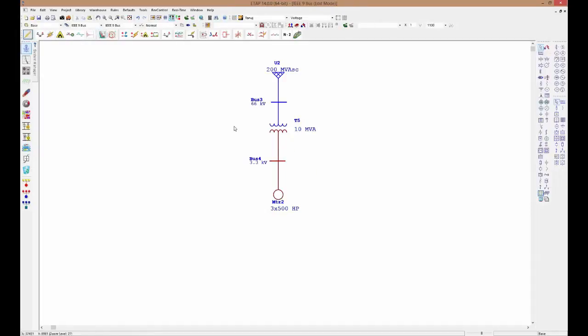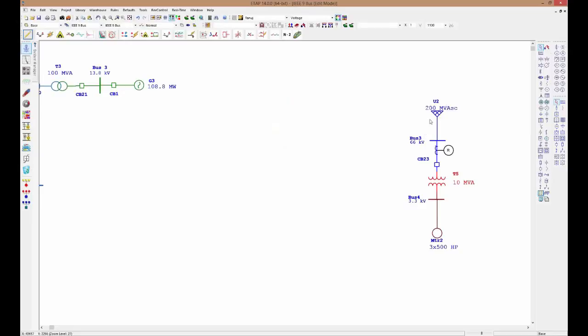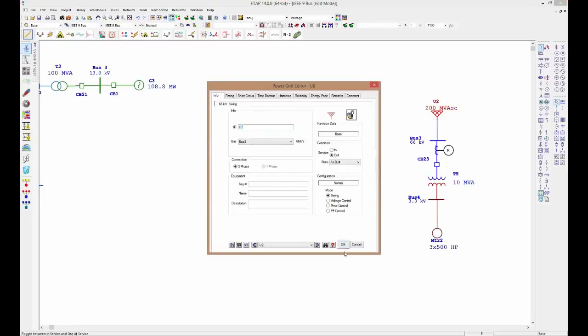So as you are essentially performing different types of calculations, you can start adding layers of information into the program. If I was adding protective device information, I would essentially add the relay and the CT here, and then go ahead and specify location of a breaker, and then just quickly build the protection system in this manner. So I'm going to go back to the system that I have here, which is an IEEE